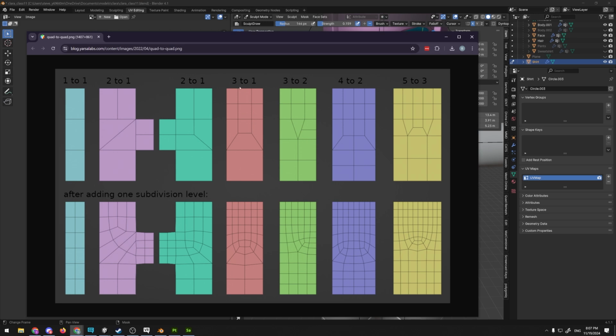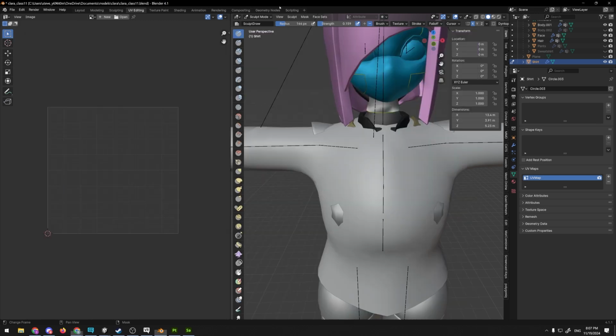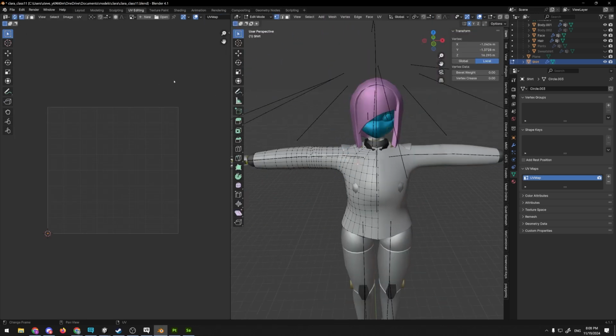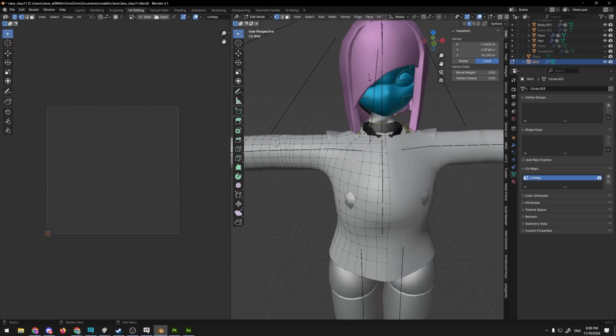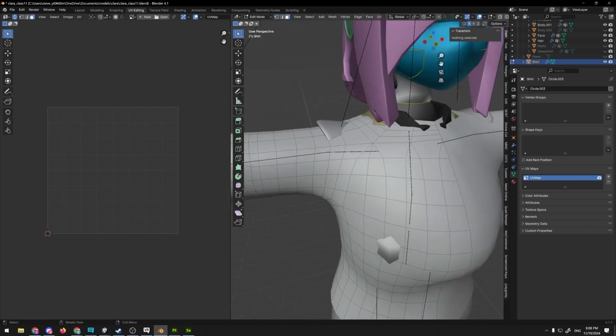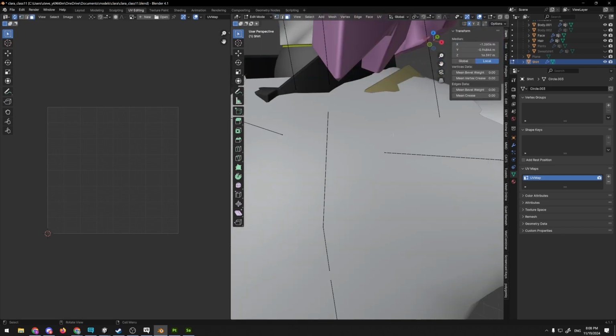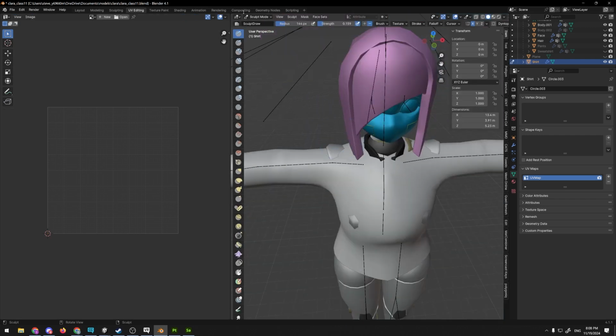This 3:1 is a really good example of how, if you go from 3 wide to 1 wide, you do that in a way that completely avoids any triangles. You use this sort of pattern with this trapezoid shape. You'll see these sorts of trapezoid shapes very commonly in modeling. And in fact, if I were to take some of my existing mesh and subdivide it, you would actually see a lot of these triangles automatically converted into those trapezoidal shapes, which I could actually do just to show off.